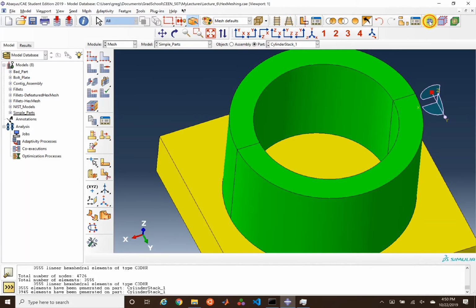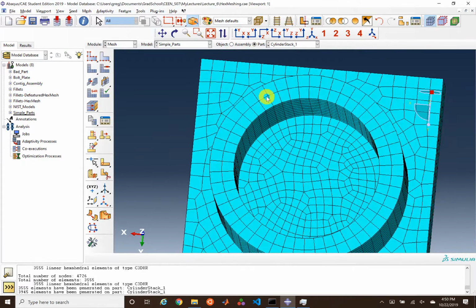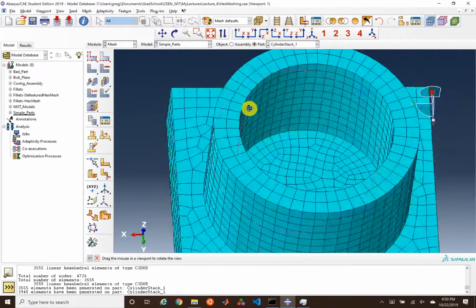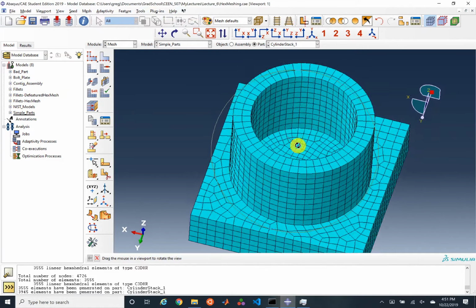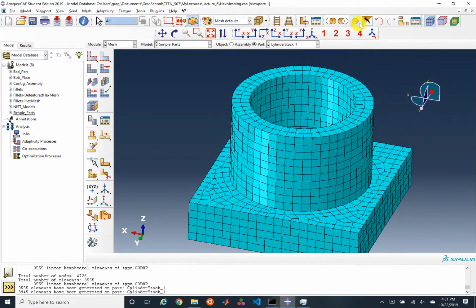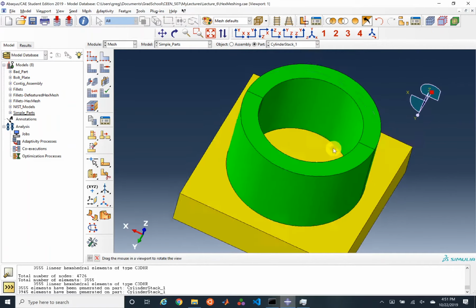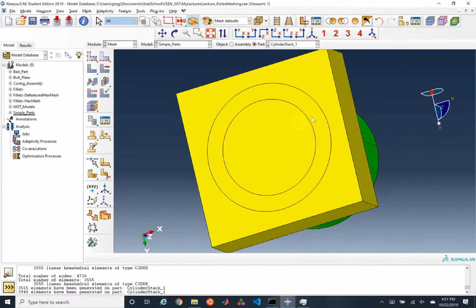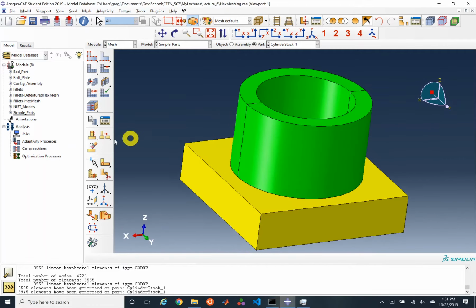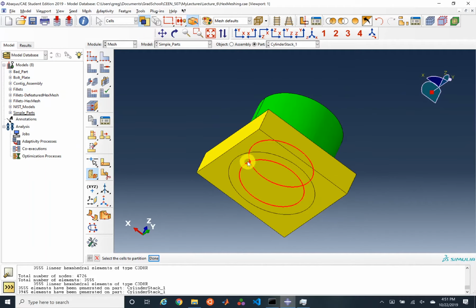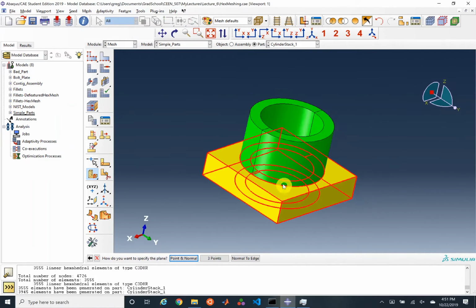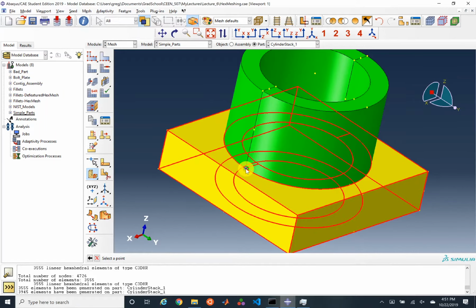If we show the mesh again, look at how beautiful this mesh on the cylinder looks. It complies as the geometry is rotating through. It's symmetric. That just looks really pretty. But our mesh on the bottom still doesn't look very pretty, and part of the reason is that we didn't propagate our decomposition through the geometry. So let's go ahead and do that. Let's select these bottom 3 cells and partition them with a point and a normal direction.